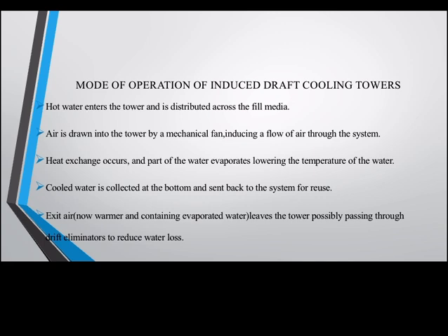The water is not discarded but taken back into the system for reuse, and this conserves the use of water by process industries. The exit air, now warmer and containing evaporated water, leaves the tower, possibly passing through drift eliminators to reduce water loss.